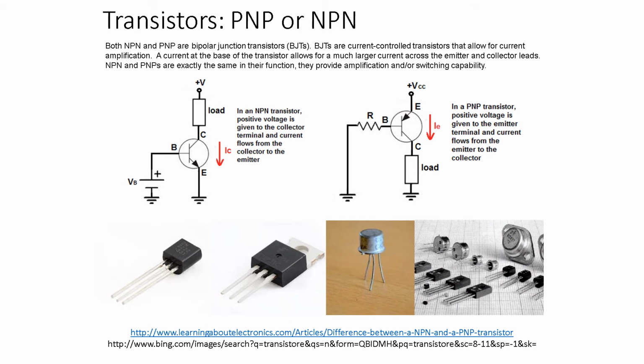We do that a lot in satellites, actually, because there's no air up in space, so we need some way to be able to dump heat out of that transistor. And the only way to do that is with a surface contact, a big surface contact. And the bigger the surface contact, the more heat flow, which we have in basic thermo. And so that tab in the back also allows for a larger surface area for heat to flow out of the transistor, keeping it cool, because these overheat relatively easily if they're not properly taken care of.